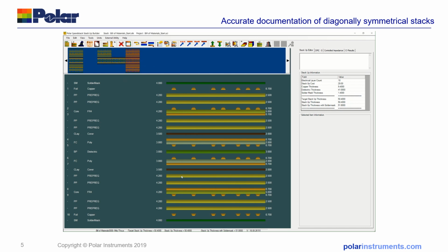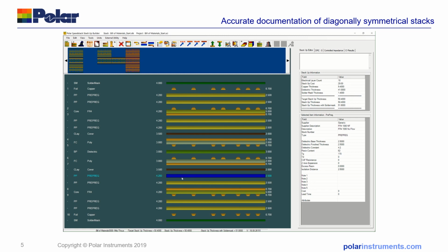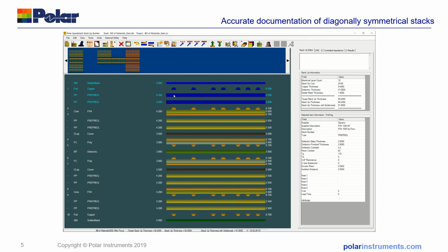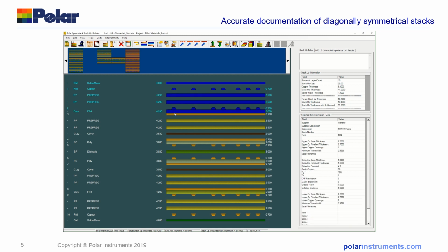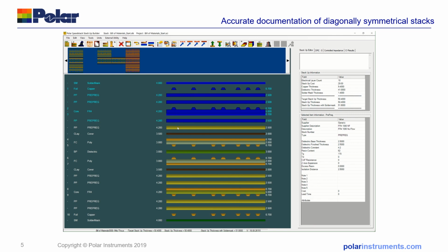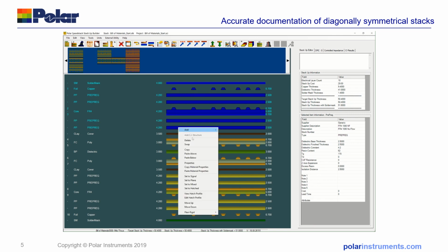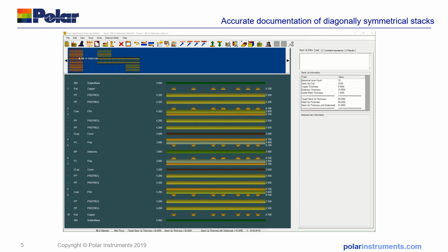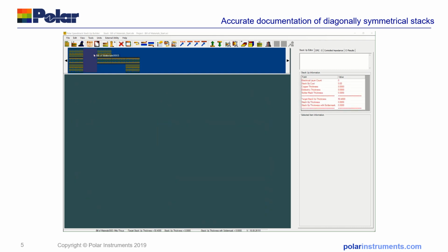So I'll complete that now, hold down Control, select, let's select these on the top, so I'm going to deselect that. Select all the materials above the flex portion, right click, disable, and now you can see in the navigator the bill of materials, a gap for clarity.